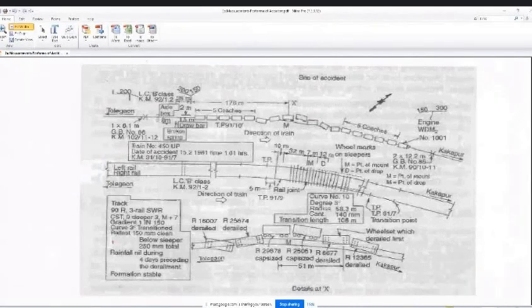Right. Now, ballast cushion. Here it is mentioned 150 mm clean, below sleeper 250 mm total. So, what is ballast cushion? Say, this is the track. Under the track, the sleepers will be there, directly it will not be there. So, ballast cushion, you have to measure from below the sleepers. Say, this is the rail.